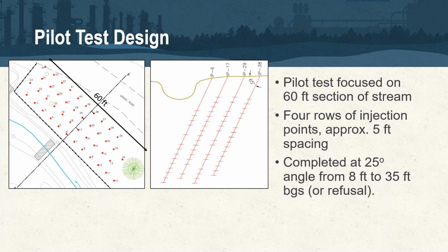And the injection volumes are going to vary depending on the geology. So if you're working in a clay or a silt and you're on that 5 foot spacing, you might be working in 10, 12, maybe 15 gallons per interval. And those intervals are going to be spaced vertically, say 1.5 to 2 feet vertically. And as that injection spacing increases, assuming you have a site where groundwater is deeper, if you're in that 10-foot spacing, maybe you're in the 40, 50, 60 gallon range of slurry.